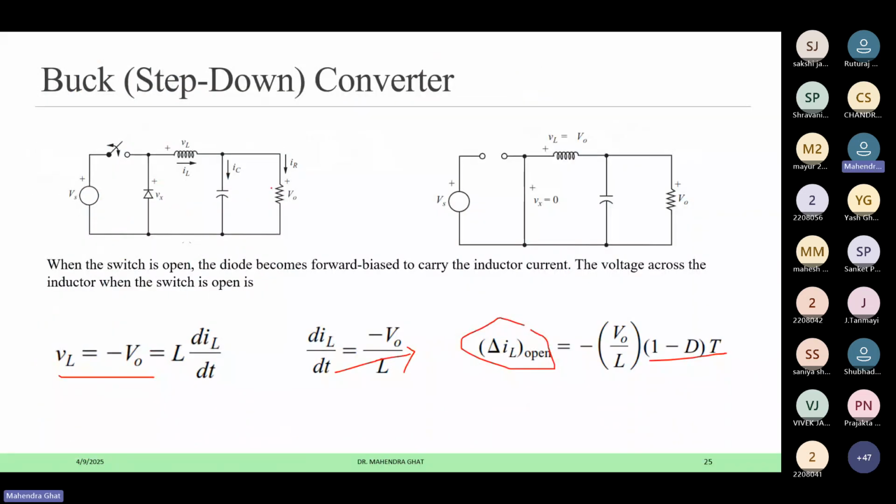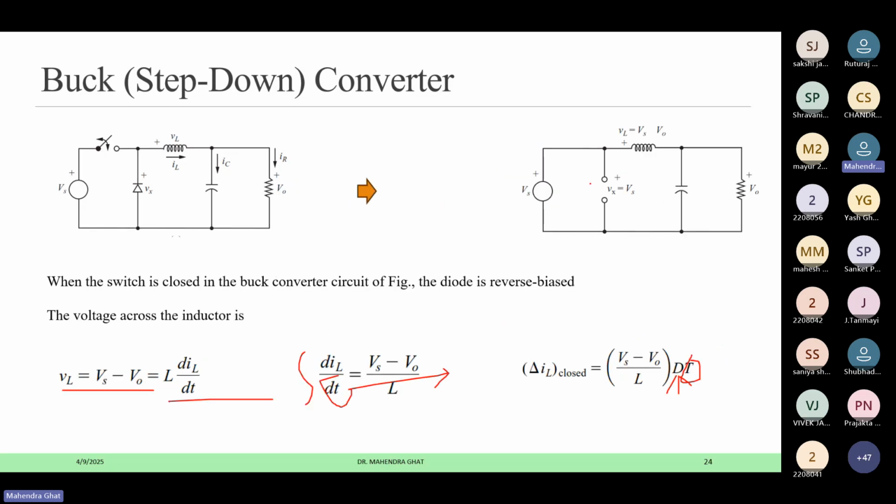you can see what is happening when this switch is open. So the voltage across this switch, if I apply the KVL here, what is the maximum voltage applied here, which equals the Vs. So this voltage is getting applied across this switch. Similarly, when the switch was closed, at that time if I apply KVL again here, this is the voltage here, which is nothing but again Vs.